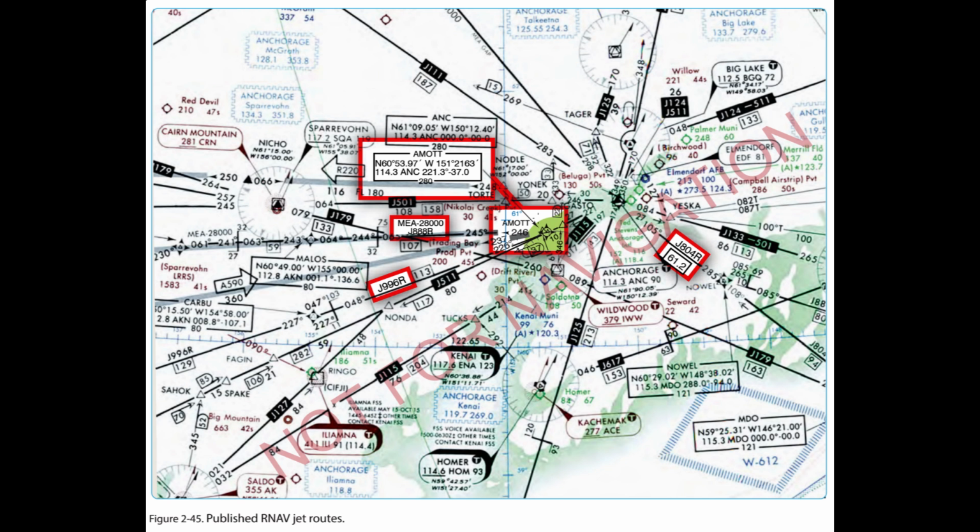2. Where applicable, 1 supplementary letter must be added as a prefix to the basic designator as follows: K to indicate a low-level route established for use primarily by helicopters. U to indicate that the route or portion thereof is established in the upper airspace. S to indicate a route established exclusively for use by supersonic aircraft during acceleration/deceleration and while in supersonic flight.